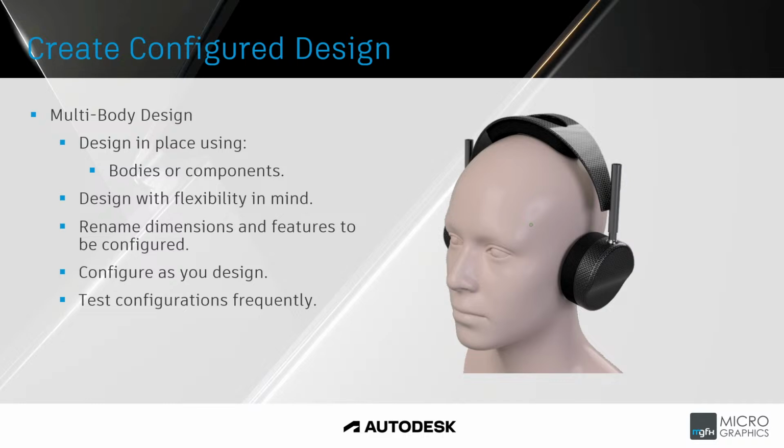Then what is very useful, or what helps, is to configure as you design. So in the case of the headsets here, I've based all of the ear cup dimensions off of a single sketch. And so as you create, let's say, the revolve to create the sponge, there may be dimensions for that revolve that will change, or dimensions from that sketch that will change to make the sponge thicker or thinner, and adjust the dimensions of the sponge. Add those to the configuration table as you create it.